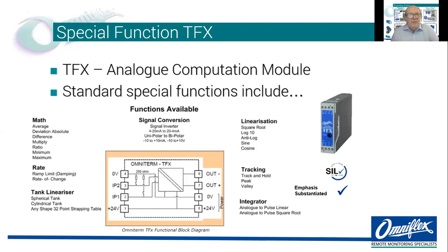The TFX is a special function analog computation module, and it covers a large array of functionality for signal conditioning on the plant. Signal conversions, inverters, unipolar, bipolar outputs, linearization, math functions, rate of change, tank linearization functions, tracking, so it'll do track and hold, peak and valley pickup, and integration. So it'll give you a pulse out either to linear output or square root. So for totalization type applications, a useful product that can be deployed into the plant.